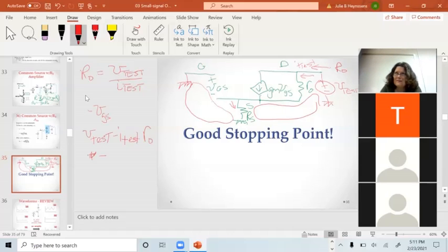That's a lot better than just trying to set the VGS constant outright, because then there are large variations. The thing you can't control in the real world is that your VGS is coming from another circuit that has gain variations with temperature and has input instability. So if your VGS on the input increases by a large amount, your output could saturate and go into distortion. So they actually have this thing called automatic gain control, where they sample the output, and if it gets above a certain level, you cut the gain by changing the bias point of the transistor.